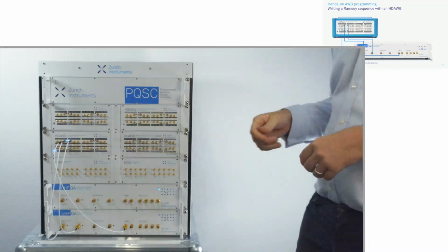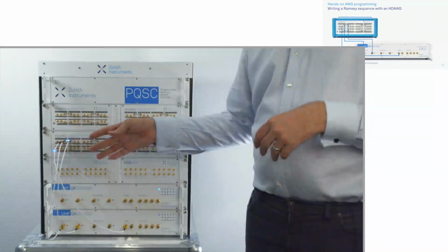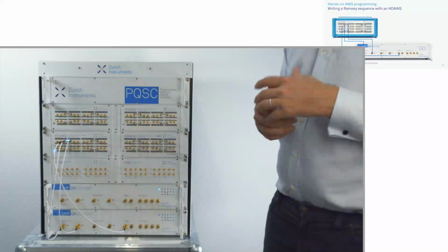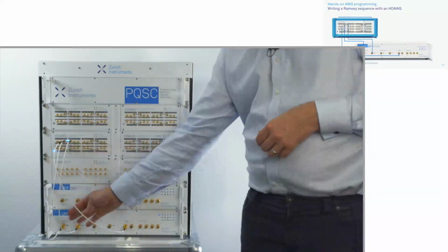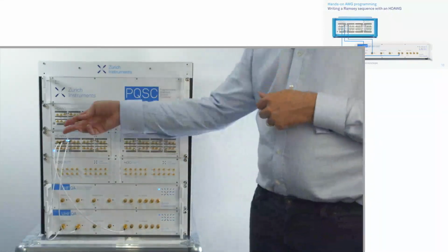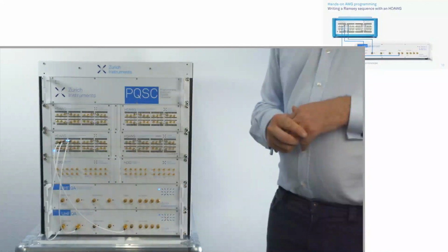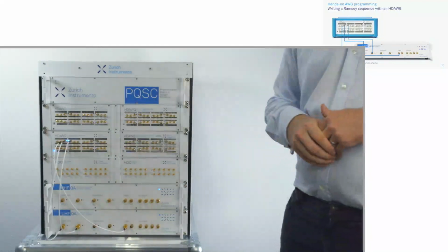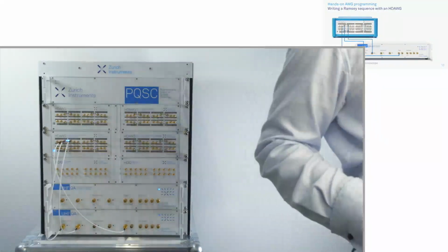And as just mentioned, we will use this AWG to write this Ramsey sequence. And we will monitor the 2 outputs, which you will see here, using the oscilloscope, which is in this quantum analyzer. We also have connected a trigger cable just to be able to trigger the result acquisition. So and with this now, let's go right into how do we control these instruments.